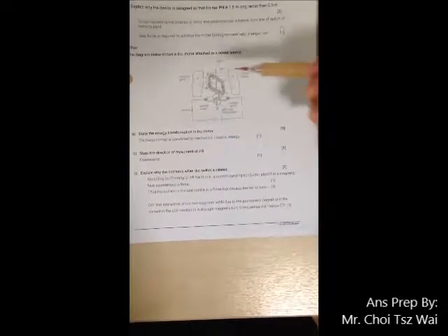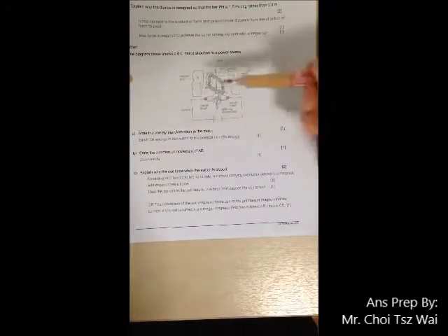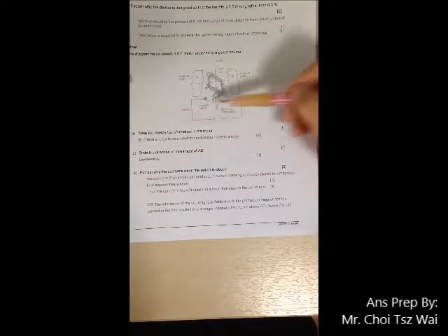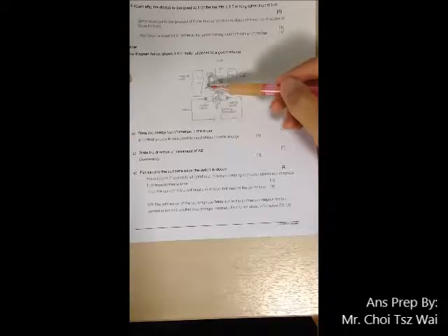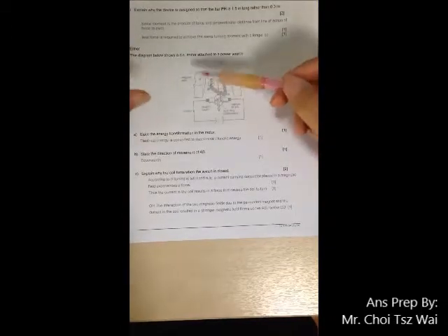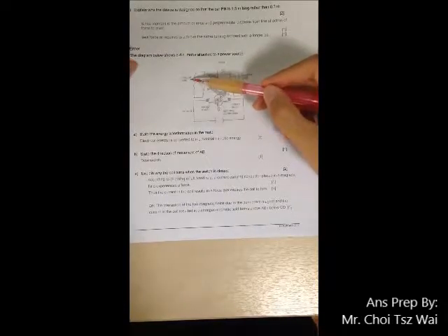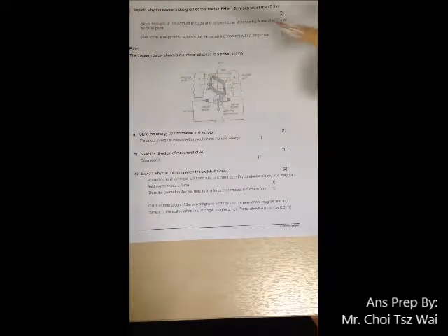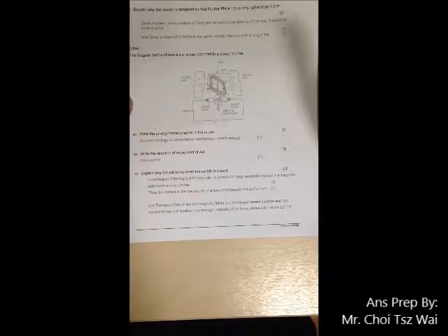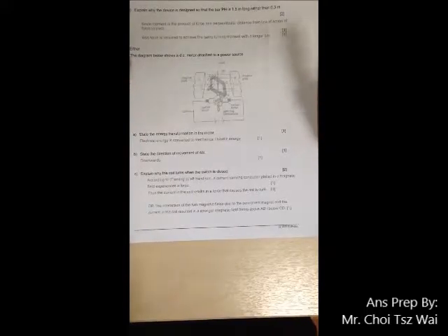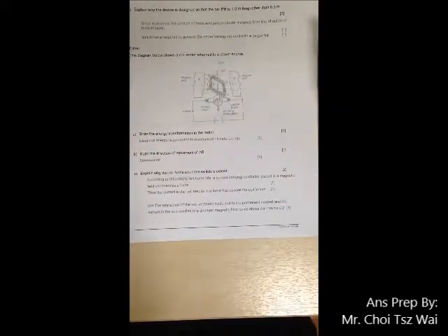Okay, what I'm looking for is that you have to highlight to me that when the circuit is switched on, the current flowing through coil ABCD is going to generate a magnetic field. This magnetic field is going to interact with the magnetic field from the magnet poles. Okay, and the interaction of these two magnetic fields is going to cause upward and downward force, and hence the coil turns. I want to see these few key points. I don't want you to just state Fleming's left hand rule. Okay, that's not good enough for me.